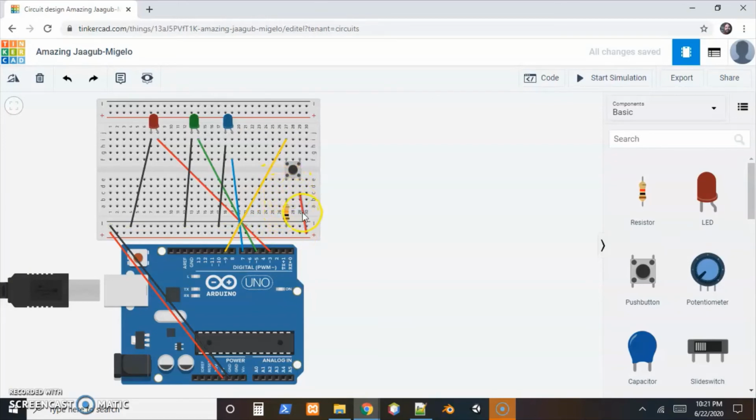It's there because the voltage can't do anything in the circuit, so it comes back to ground, but we don't want the full voltage coming back to ground, so that resistor, a pull-up resistor, just burns up some of that voltage, is what that resistor is for. And then when we are pushing the button, well, then that 5 volts can flow through here, and it'll come back this wire, and we'll be able to detect it on pin 9.